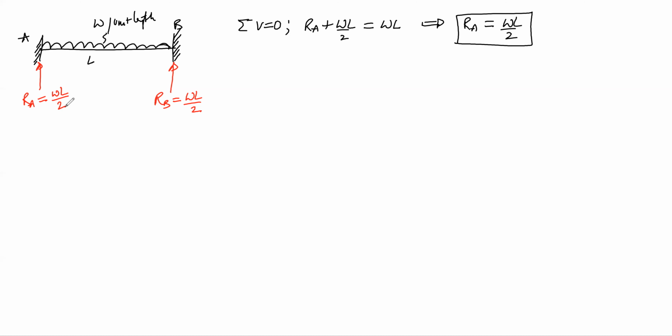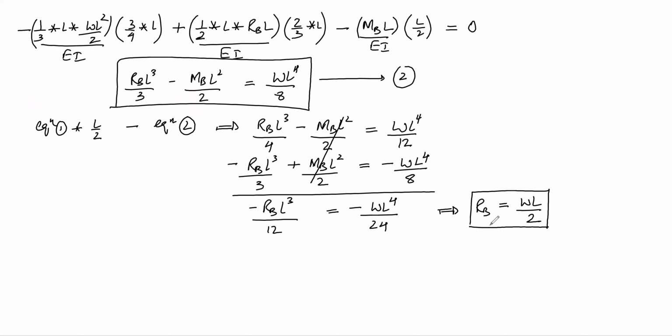And also using the two equations we have calculated RB. So by substituting RB in any one of the equations, we can calculate the value of MB.